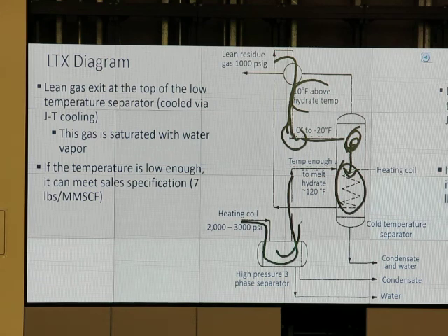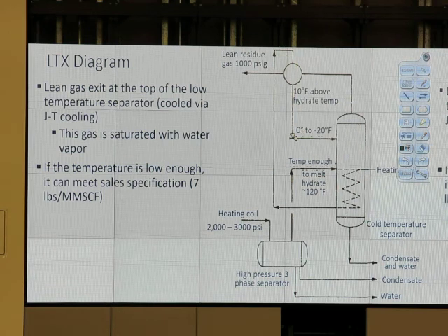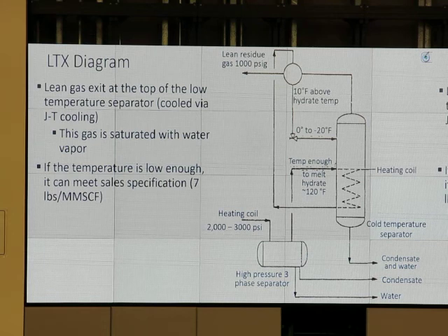You're treating the gas, so it's almost a different system than your line heater that you've been talking about, where you want the gas dry at a glycol unit somewhere down the line. So you're trying to do it all in one unit right there. And that makes the difference of why you're allowing that hydrate to form where you still have a lot of heat.